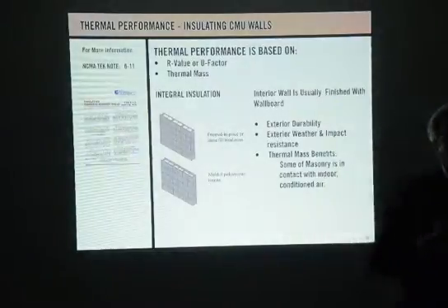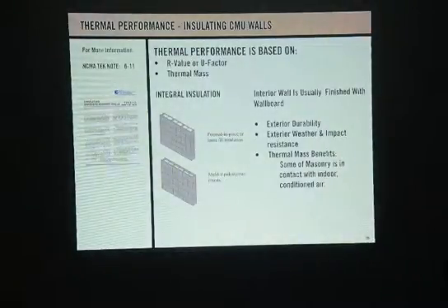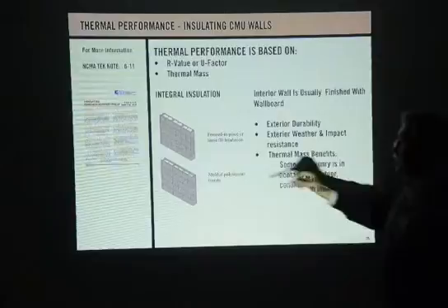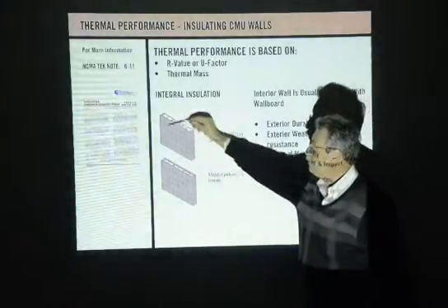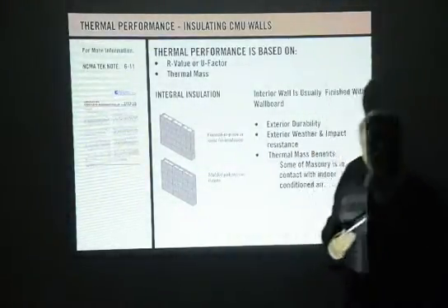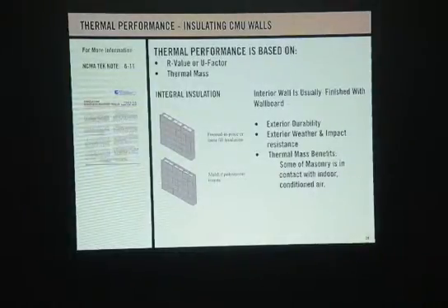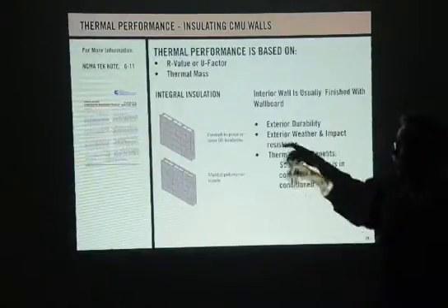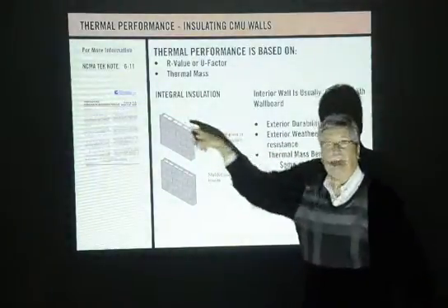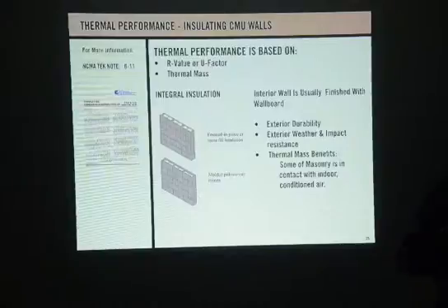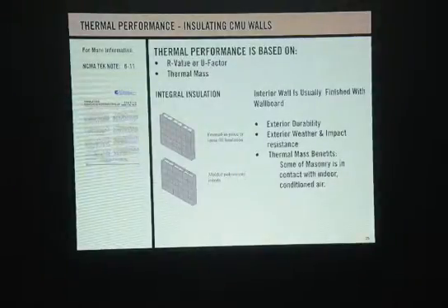It's a good product, but we don't have any solids issues. This is 100% solids. Foam in place is about 90% solids. So Mike, what does that mean? It means there's potential for shrinkage, deformation over time, and that's where condensation comes back into play.